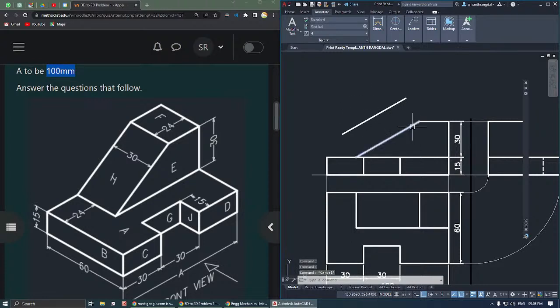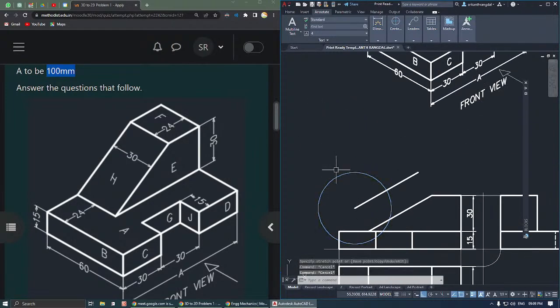Okay, so wherever true length is there, we have taken a parallel line, and then thickness of this will remain the same. So this same thickness, I'm taking a circle, you can see center point is here, it is passing through this point. So radius of this is now equal to the length of this edge. So same length we need to take and we need to mark from here. And here we need to draw a line perpendicular to this line.